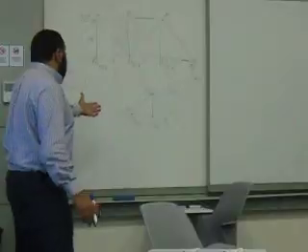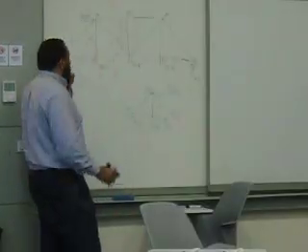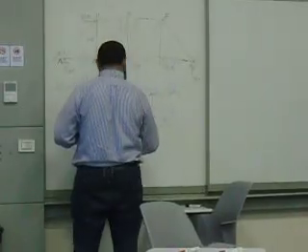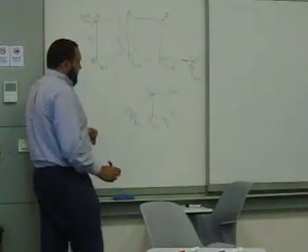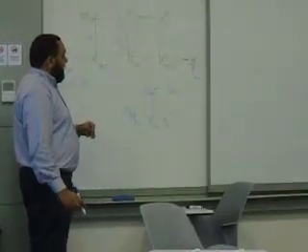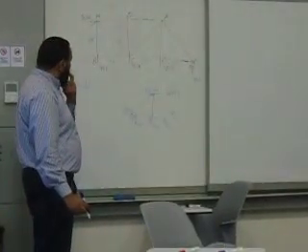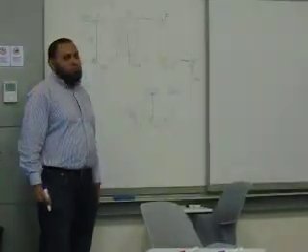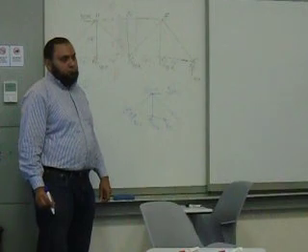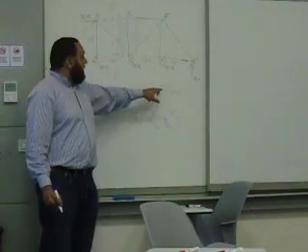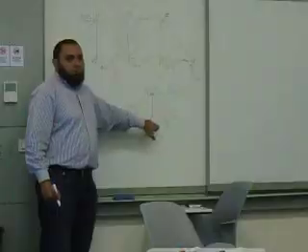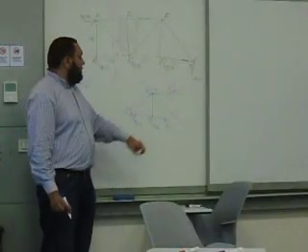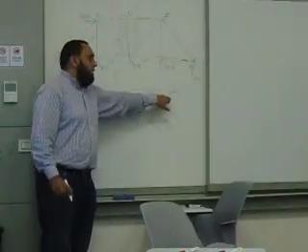So here for example, this is point H, this is B, this is A. If I take a moment at B, I will have FHG and FHC as unknowns. But if I take a moment at H, I'm getting rid of these two and I'll get this one. Sigma Fy, I'll get this one. Sigma Fx, I'll get that one.